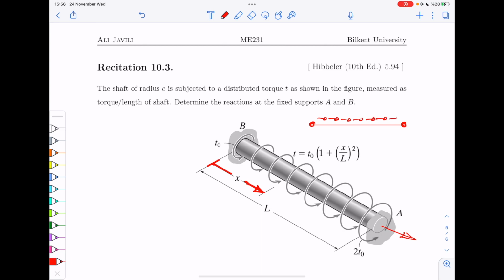So this is the T that we have through the shaft. Now, think of it as just being forces. If you had a distribution of forces like that, you would need two forces in the opposite direction on both ends to compensate for it, right? In this case, this would be TB and TA. Does that make sense? Which would be clockwise.